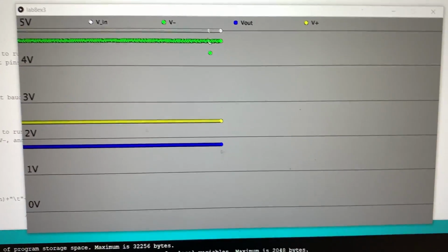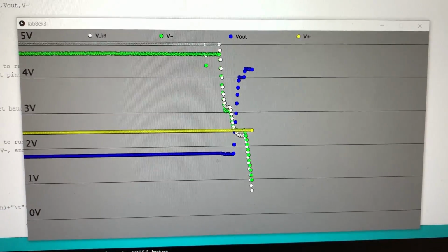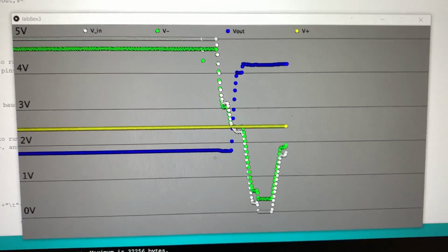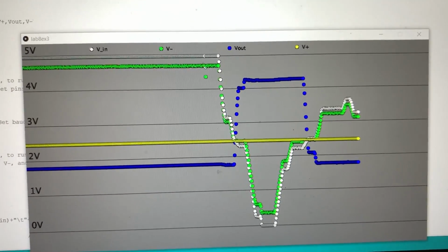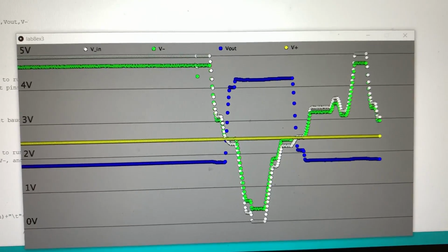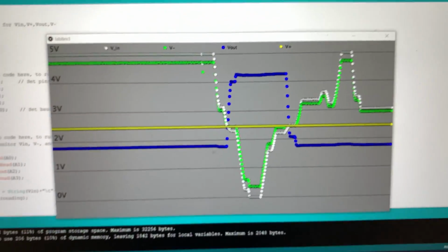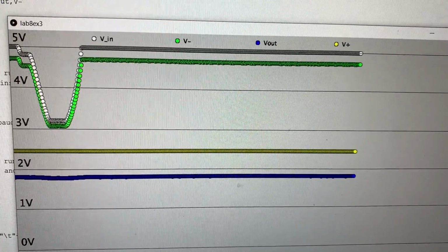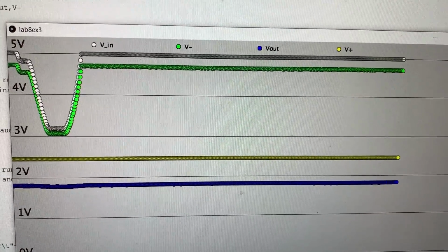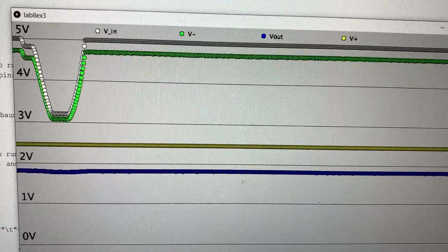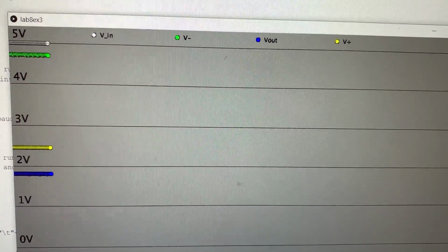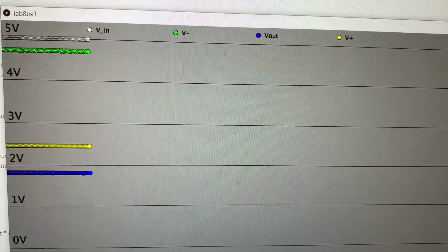You basically know that this is inverting because you can see that the V out and V in are out of phase. But this is not what we expected because the gain was -10. In our case, that's not true. This is because our negative VCC is again 0 volts instead of -5, so we can't get that clear -10 gain. Lastly, the thing I want to mention is that our VN is also from 0 to 5 volts. So that is going to have an effect on how it should ideally operate in this circuit and also the last circuit exercise too. I forgot to mention that earlier.